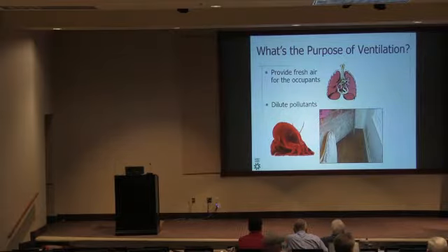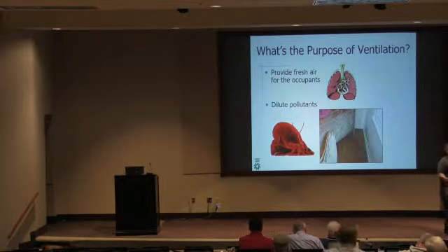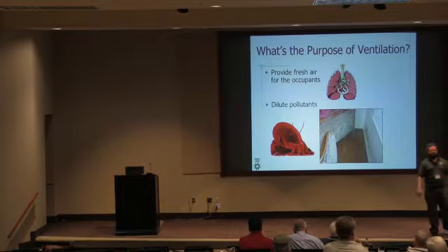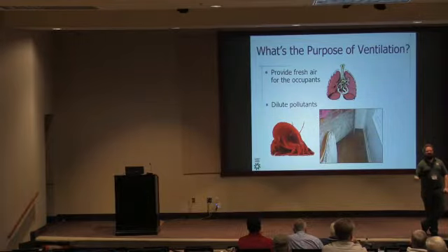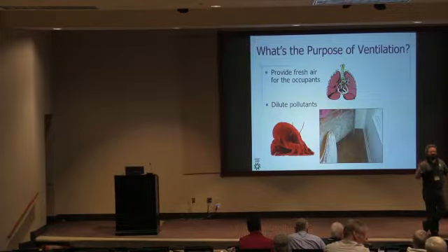Yeah. Nest is good. So I'm kind of getting to answering that, which basically what I'm saying is, when are our HVAC systems the most efficient? When they're not running, when they're turned off, that's when they use the least energy. So, we actually had this conversation again on Wednesday with a building official for the city of Atlanta who was doing a renovation on her home, and she was like, wait, you're telling me I don't just want to keep my thermostat set to 70 all of the time? We said, no, you want to use setback. She said, but doesn't it cost more to try and cool the house back down after it drifts?